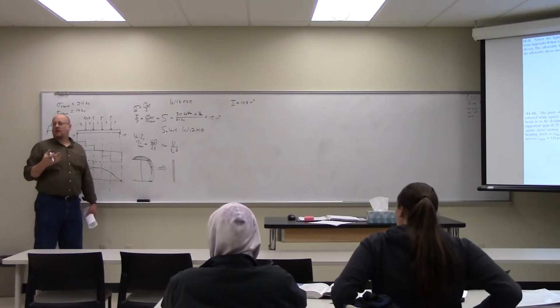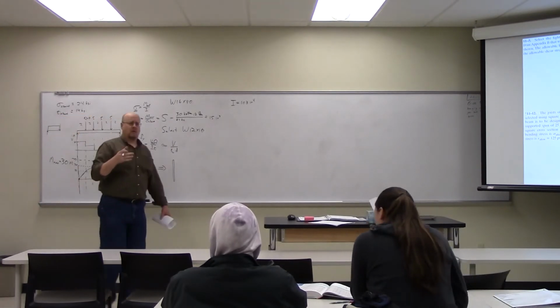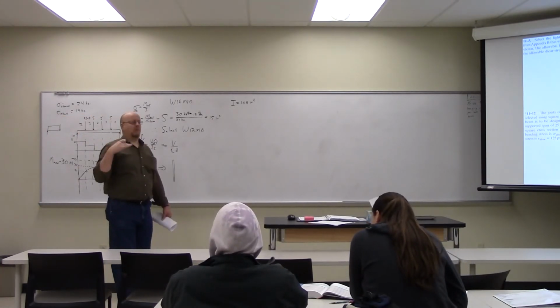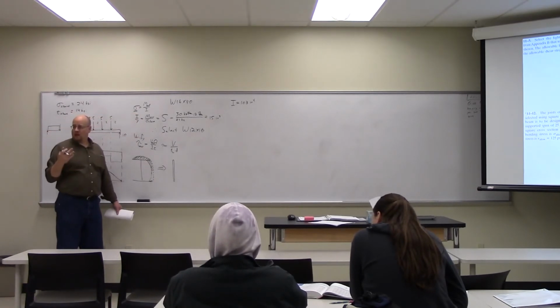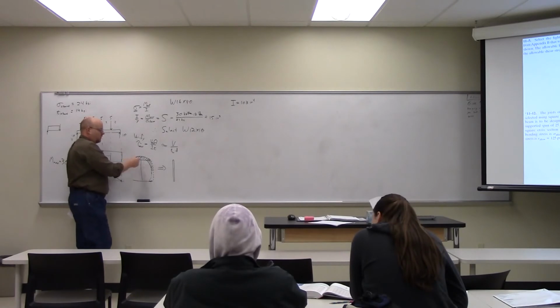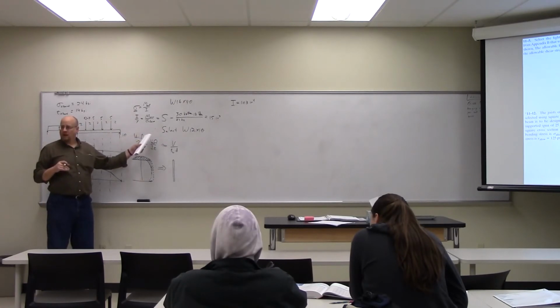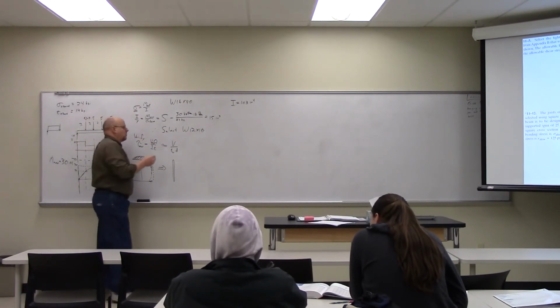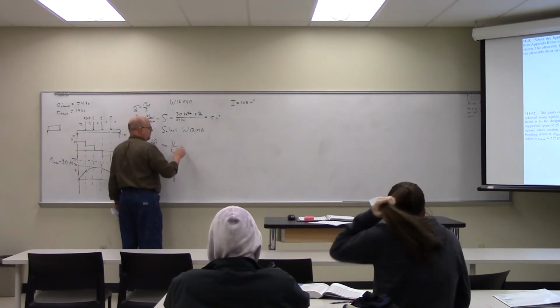I would only need to calculate Q for that, and I don't think they calculate Q in there, do they? Because Q would depend on the top, would just be the top half. But you can calculate, knowing it gives you the thickness of the flange, the thickness of the web, the width of the flange, the height of the web. So you can calculate your Q, your I, everything. But generally speaking, this is going to give you a more conservative, or a faster result.